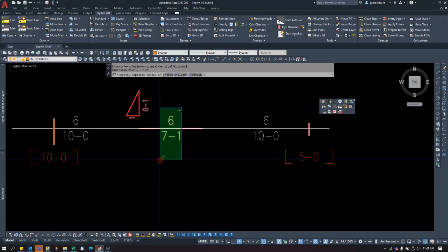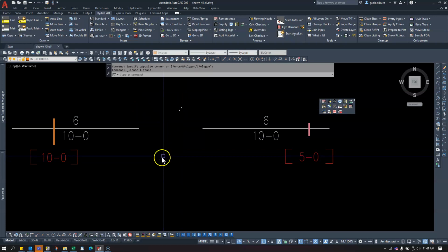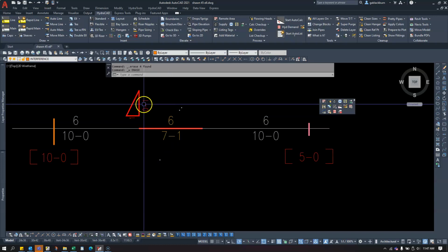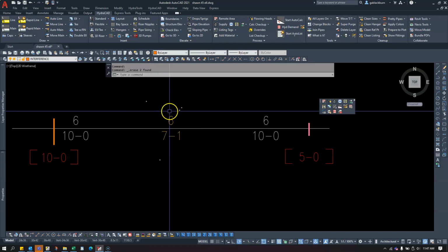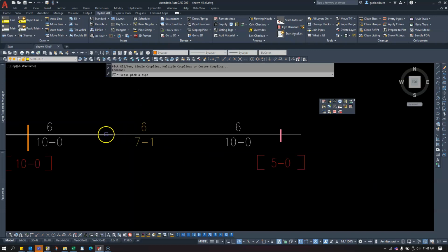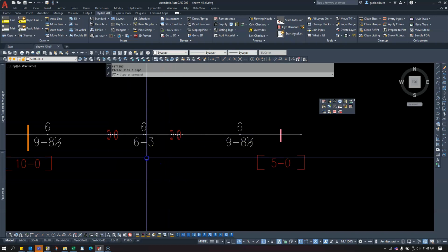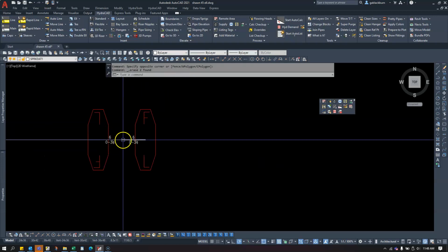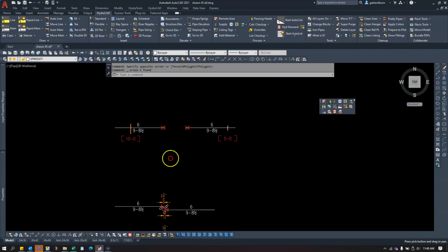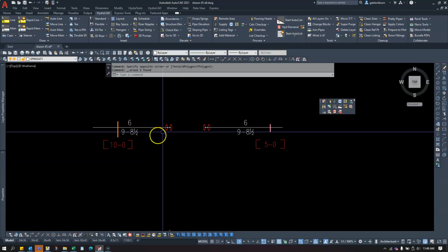I'm going to erase this pipe. Actually, I'm not going to erase it. Let's undo that. Let's get rid of the pitch. Delete that, and yeah, let's do that. So I'm still set up for my 45-degree elbows and tees, so I'll pick 45 elbow tee, and I'll break one in over here, and I'll break one in over here. Okay, I'll get rid of this, and now I'm going to adjust this length and distance so that it's 2.5 inches based off this instead of 3.5.